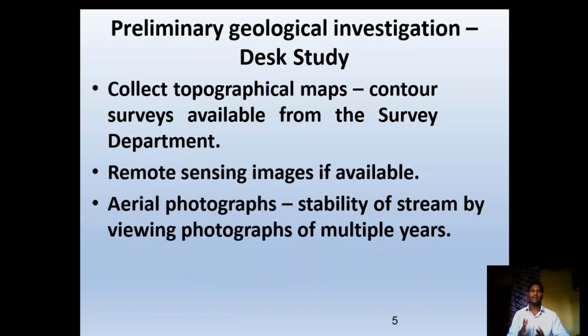High investment is needed to construct a bridge, so it's important to make the right decision first. The preliminary geological investigations or desk study: you have to collect topographical maps, contour survey available from the survey department, remote sensing images if available, aerial photographs, and check the stability of the stream by viewing photographs of multiple years.